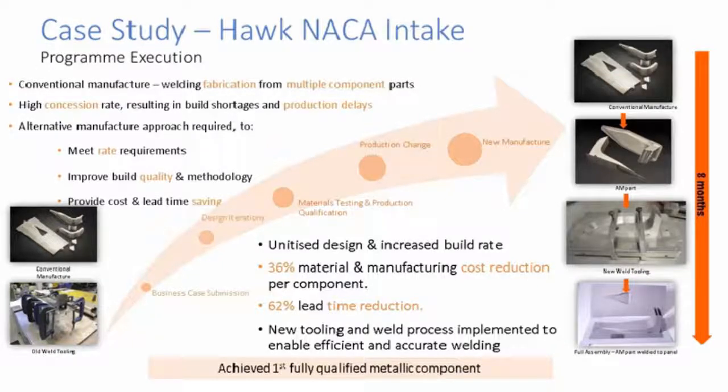In the next slide, we're going to look at a case study of SLM activity in the military aerospace environment. It's the Hawk NACA intake. A NACA duct is a common form of low-drag air inlet design originally developed by the US National Advisory Committee for Aeronautics, the precursor to NASA, back in 1945. The original part was of conventional manufacture, welding fabrication from multiple component parts.